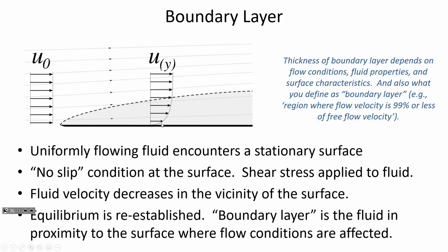Remember, laminar conditions are those associated with low velocities, where the flow is smooth and quiescent, where we don't see turbulence. There aren't eddies or swirling countercurrent flow vortices. The water's just going in a normal direction. Remember back to the lab, that blue dye that we were injecting into the Osborne-Reynolds apparatus. When the velocity was slow enough, it stayed together as a stream, but then as we opened up the valve and the velocity increased, it was being mixed.